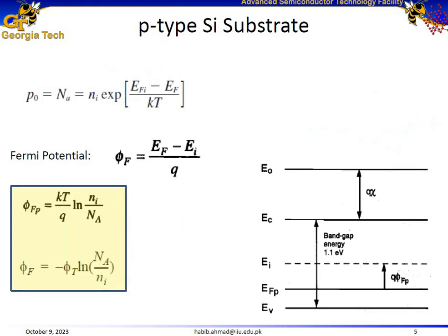For today's lecture, we will focus on the p-type silicon substrate. If the substrate is p-type, the drain and source would be n-type, implying that we are actually referring to an n-type MOSFET. So in today's lecture, we'll focus on a metal oxide semiconductor structure where the substrate is p-type.